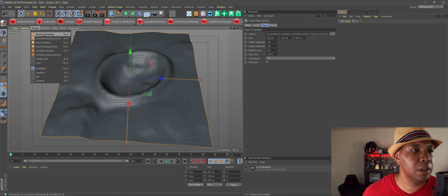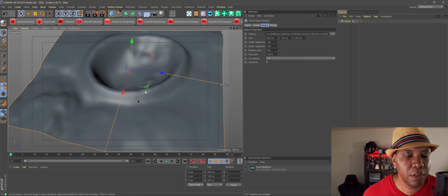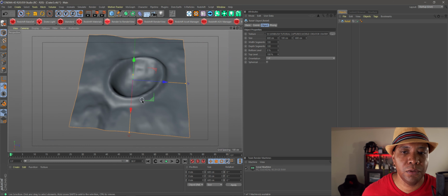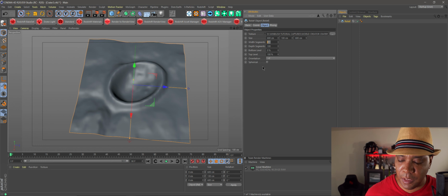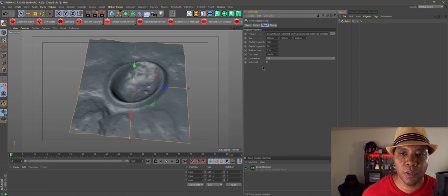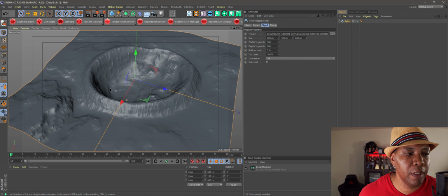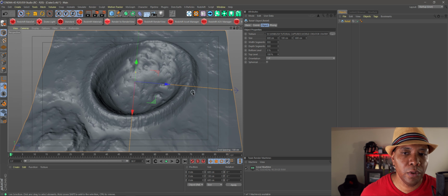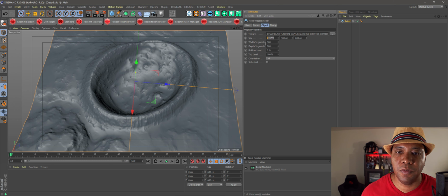Let me click on regular shading, no wireframe. So it doesn't look quite like how it does in World Creator. That's because we have to add a little bit more depth to it. So my width segments and my depth segments, I'm gonna just go overboard and do 900 by 900. Add a lot of detail in here to make it really dense. And I'm also gonna make it a little bit larger. I know World Creator works in meters, and Cinema 4D by default is in centimeters, but I'm just going to keep it at default centimeters.